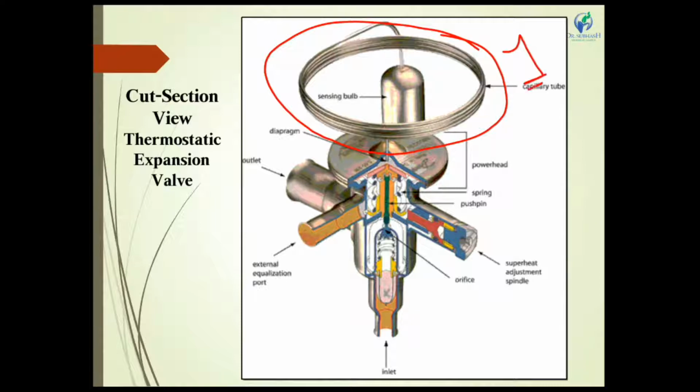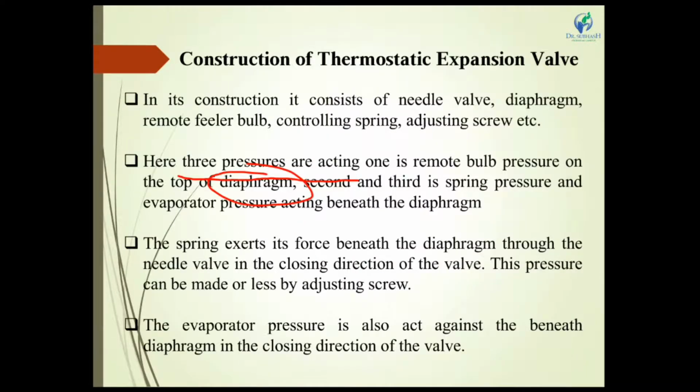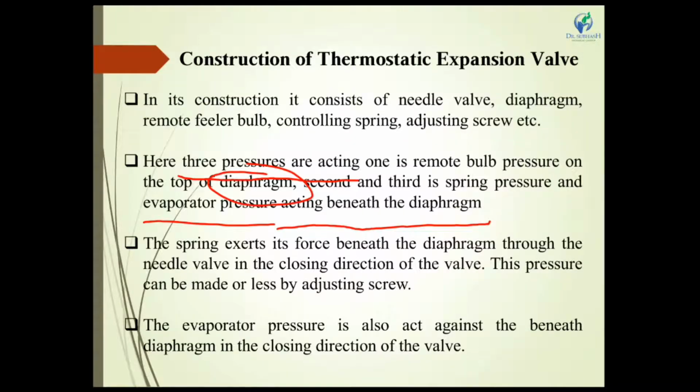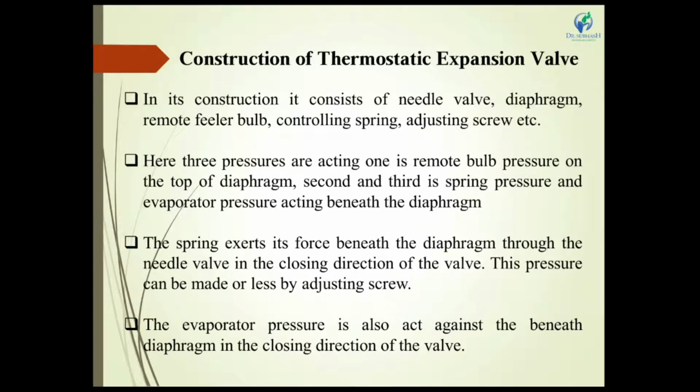The first pressure is the spring pressure. The second and third pressures are the evaporator pressure and the diaphragm pressure acting on the diaphragm, meaning there is an outlet position and a diaphragm pressure. It is a power head. Three pressures are acting on the thermostatic expansion valve.